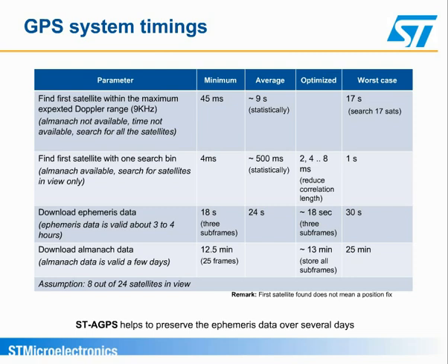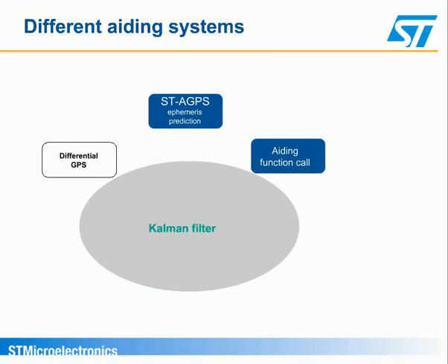This piece of software calculates the ephemeris data containing the satellite orbit information for each specific satellite for some days in advance, and stores it in the system for immediate use. ST Microelectronics provides a GPS library with the chipsets. This library contains all the necessary software functions to calculate a position and can be used within a customer software application. Assisted GPS reduces a cold start to some seconds running an additional software task.